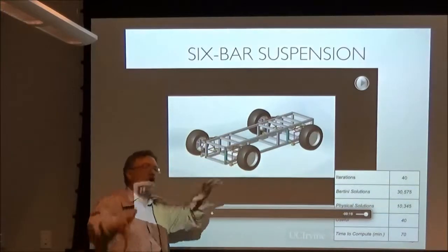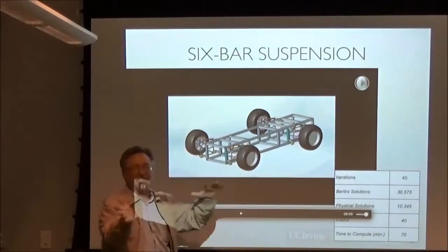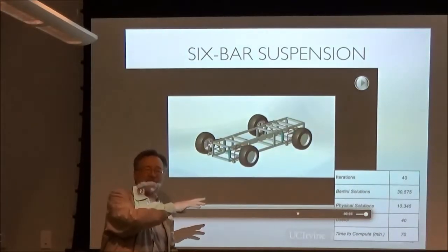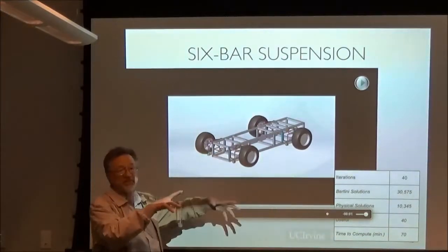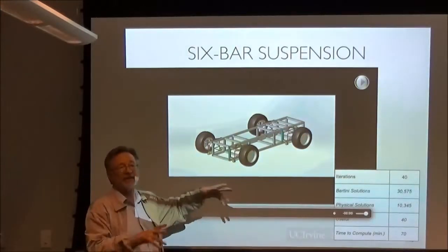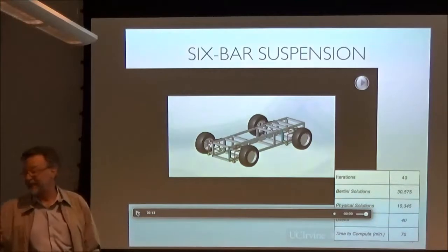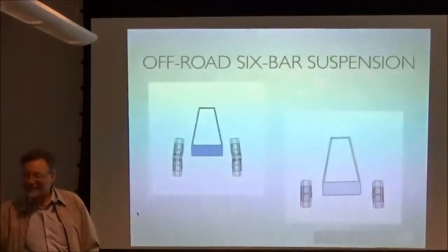So instead of rolling this, when you make a right turn, your center of gravity, by definition, causes the car to roll away from the turn. By having your suspension lower the right side, you use the weight of the car to counteract that centrifugal force. That's the idea. We have yet to see it actually work.